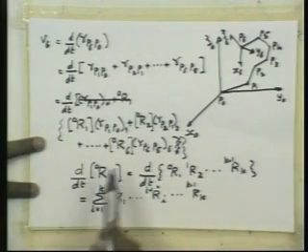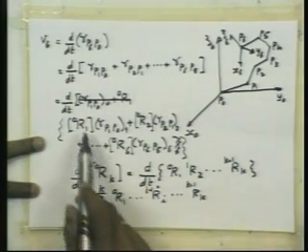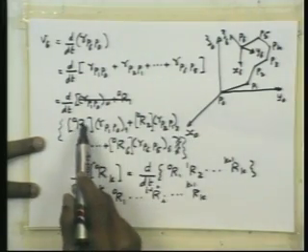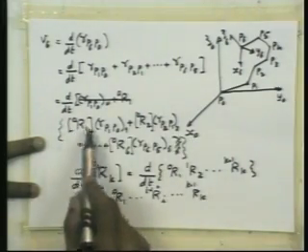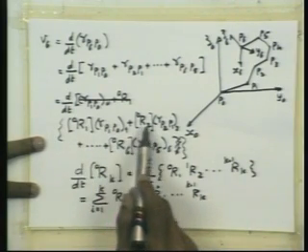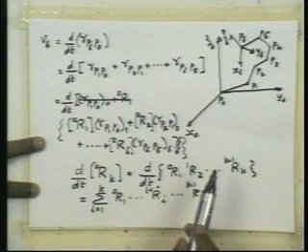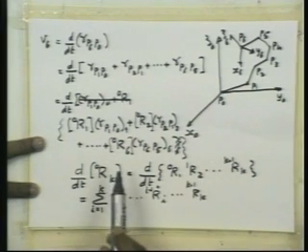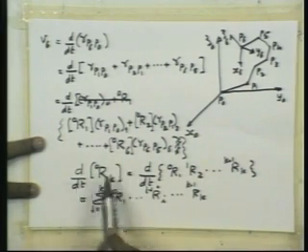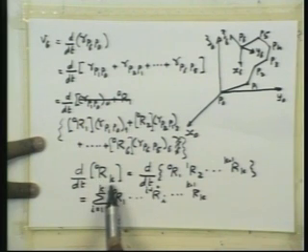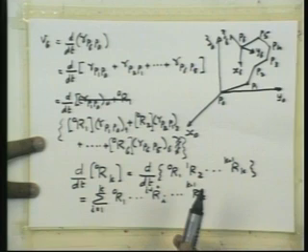Okay. So, when we differentiate this with respect to time, this will be simply the time derivative of this matrix into this fixed vector plus the time derivative of this matrix into this vector and so on. So, we will have this general operation of taking the time derivative of a rotation matrix of this form, a rotation matrix which takes vectors from the kth reference frame to the 0th reference frame.